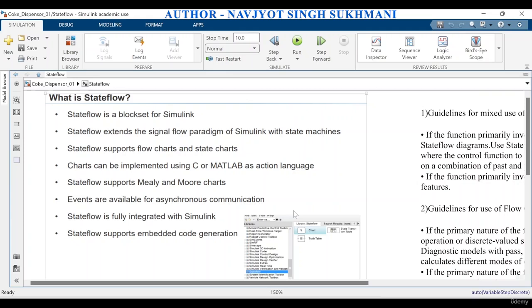Simulating and debugging capabilities during runtime are beneficial to analyze and get the desired system behavior and performance. Stateflow is chosen over Simulink to effectively handle state-based, conditional, and timing-related logic. In the case of continuous changes in the system, or when the system requires complex math operations, Simulink is preferred over Stateflow.